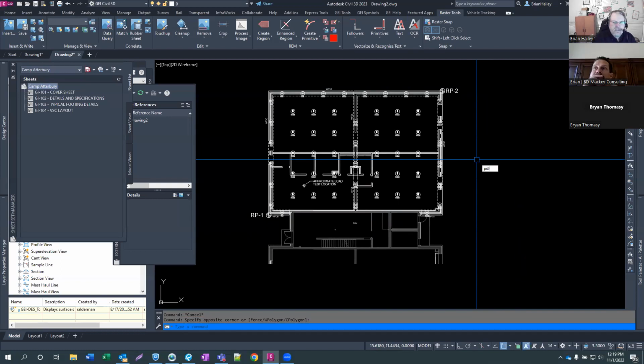Gotcha. Yeah, that's the PDF SHX. So if I remember correctly, when that's turned on and you plot a drawing that has SHX fonts, it will create invisible markups on top of your text in your PDF so that it is searchable. Because like I said, SHX is not really a font, so it shows up just as lines in your PDF.